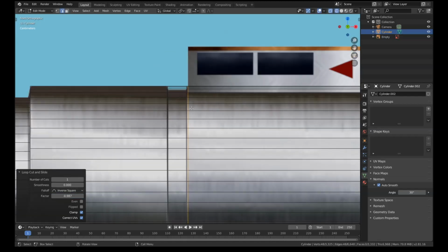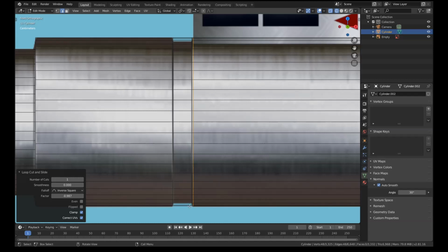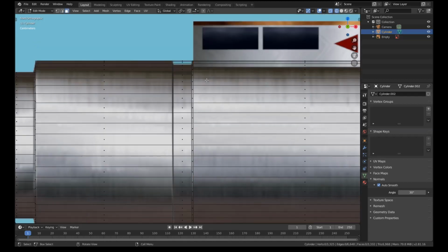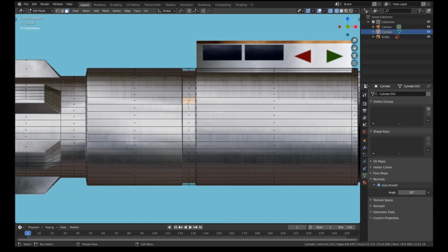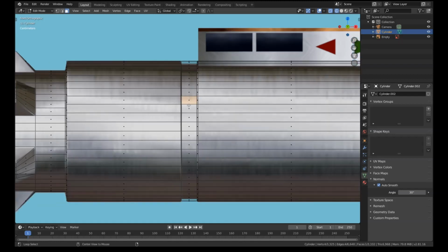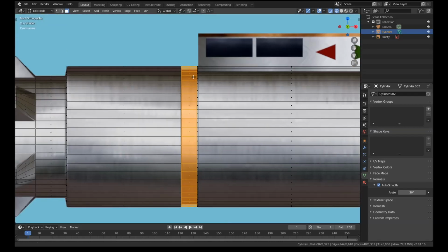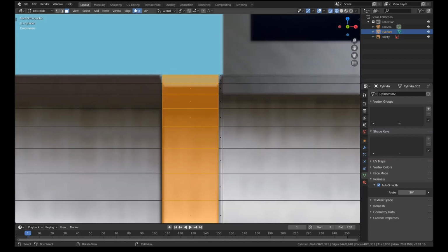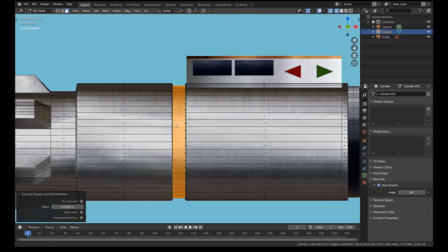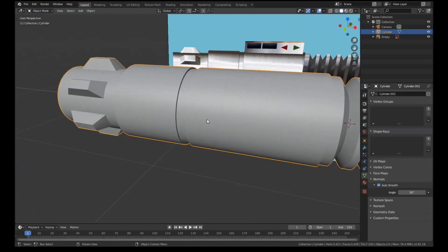And then before we extrude up this, I'm just going to deal with this little sort of divot bit here. Okay, if you press 3 and hold down Alt and just click one of the bottom or top edges, it'll select this whole loop cut. And then if we go to face, extrude along normals and pull it down until it's lined up, that gives us that little gap that goes all the way around, the little cut in section.